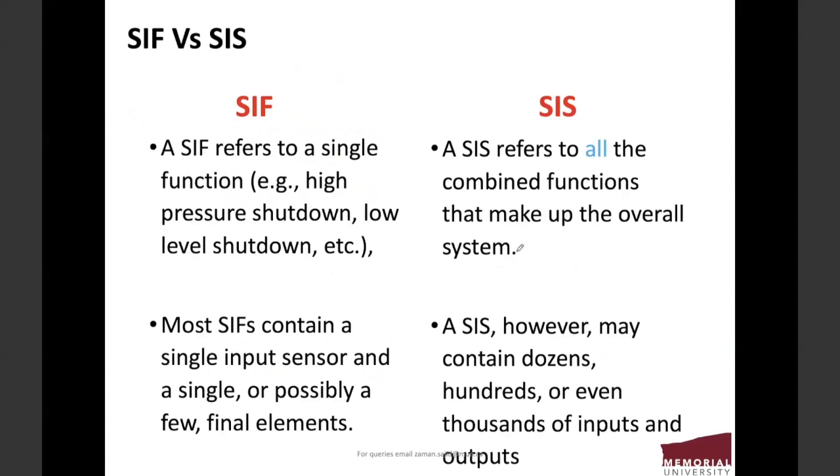This is an important slide. If you understand this, it will be easy for you to understand the difference between a SIS and a SIF. So a SIF refers to a single function. As I just mentioned, it could be related to pressure, or temperature, or a low level shutdown, where we are controlling our level.